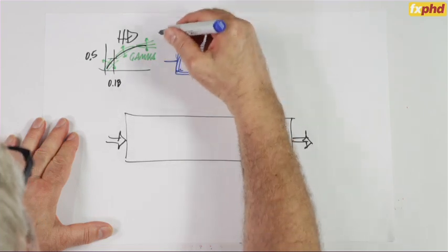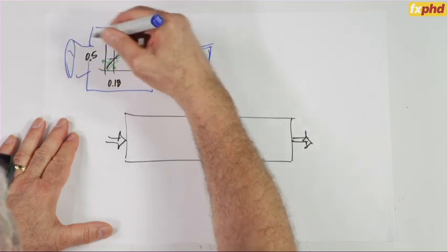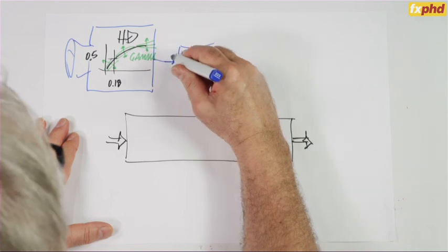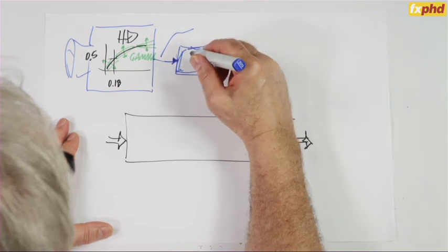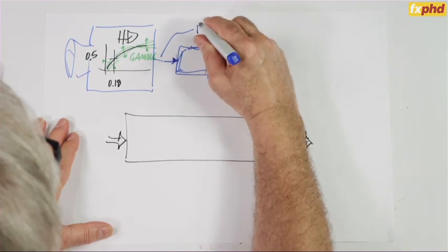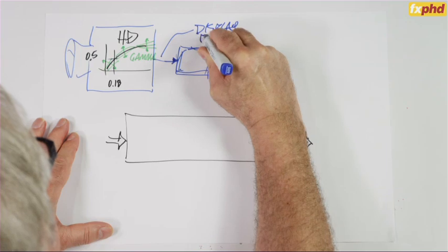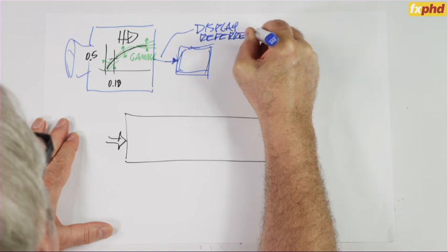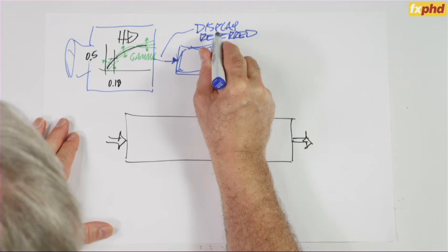So in other words, this gamma correction circuitry, which is incorporated into the HD camera, is delivering at the camera output signals which are directly suitable for application to the display. And this philosophy is called display referred. And the image data is said to be in the display referred state.